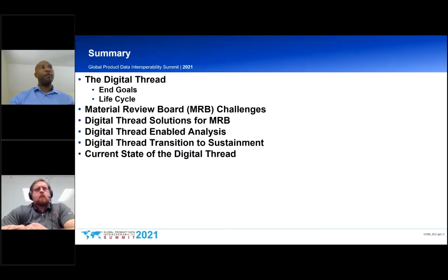So today I will be discussing the digital thread, some of the end goals, the life cycle, some of the challenges that are presented with the MRB process, which is the Material Review Board, and how the digital thread provides solutions for those problems, as well as enabling a wide variety of additional analysis. We'll also touch a little bit on how the digital thread transitions from manufacturing to sustainment, and we'll discuss the current state of the digital thread today.